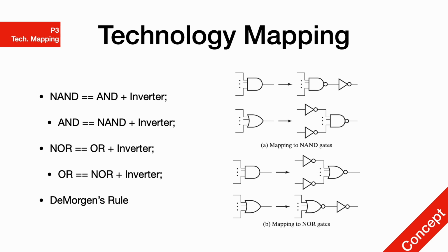In this slide, you find some of the information that you can use in real life. For example, in certain cases where you don't have an AND gate, what you can do is to replace instances where you need AND gates with a NAND gate. Because the NAND gate is essentially an AND gate with an inverter, you can add another NOT gate after it, as you can see on the right hand side. You can use this combination to replace your pre-existing AND operators, and similarly you can also replace an OR gate with a combination of NOT gates and NAND gates. This is just by applying De Morgan's law.